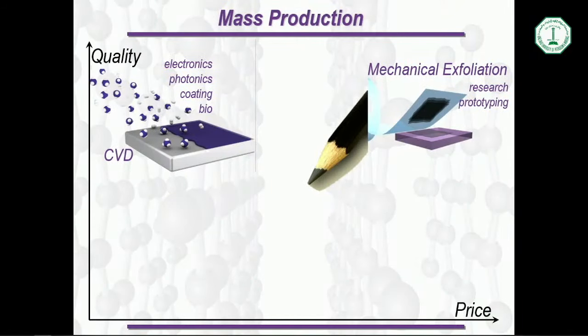So we have other ways to produce graphene, depending on the price and the quality you want to get. There is the CVD method, chemical vapor deposition, which might be very relevant for non-metallic applications. You basically run carbon-containing species on top of the catalytic surface of a hot metal, and then it just cracks into graphene. So you can use pretty much anything for that.